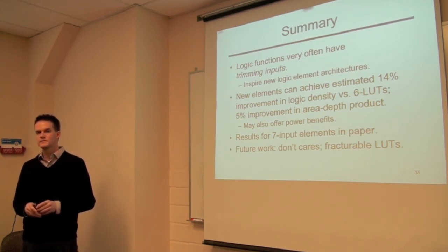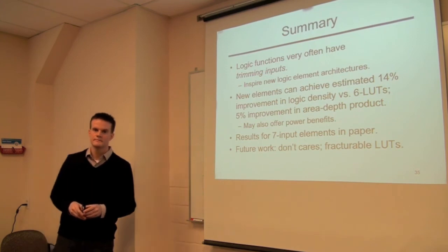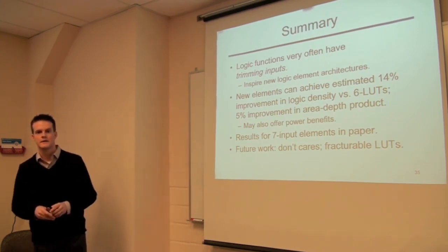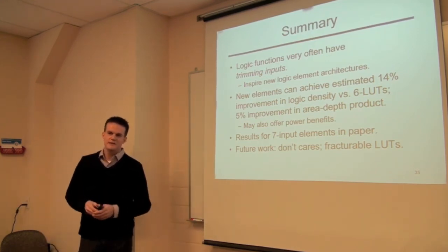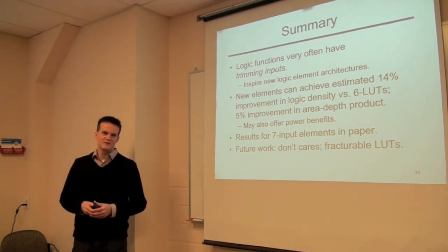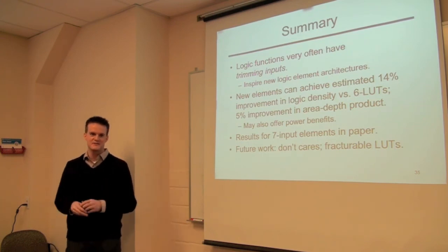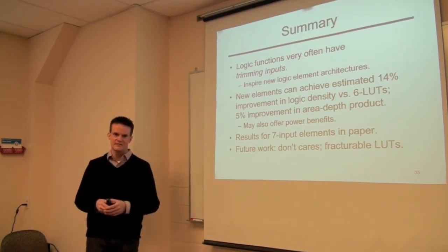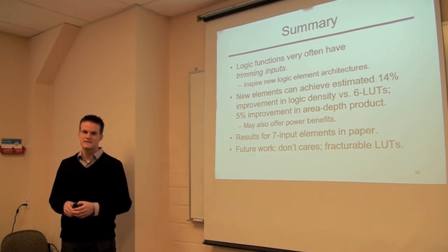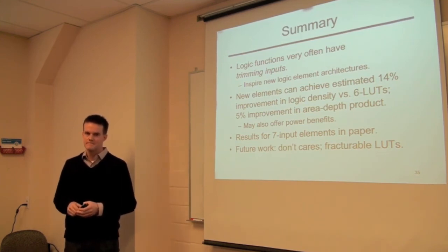It's a good question. Brayden. All right, a question from the chat room is, what's the runtime hit of the cut pruning step? We didn't even measure it. It's almost the same runtime as without the cut pruning. So it's very fast to find these trimming inputs. You're doing a fast traversal of the AND-inverter graph, and then you're basically marking some AND gates as out of it, and then what you have left, you see how many input variables you have left in it. So it's not a significant runtime hit.